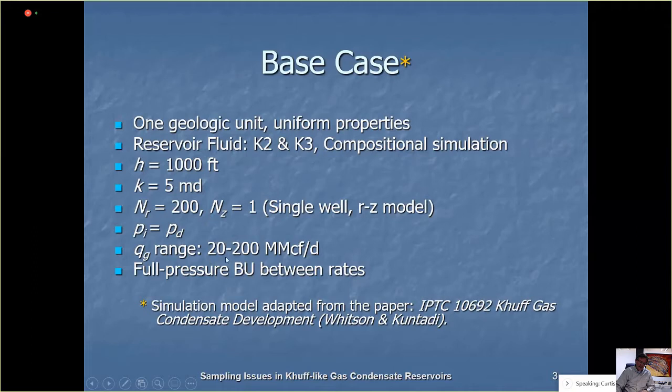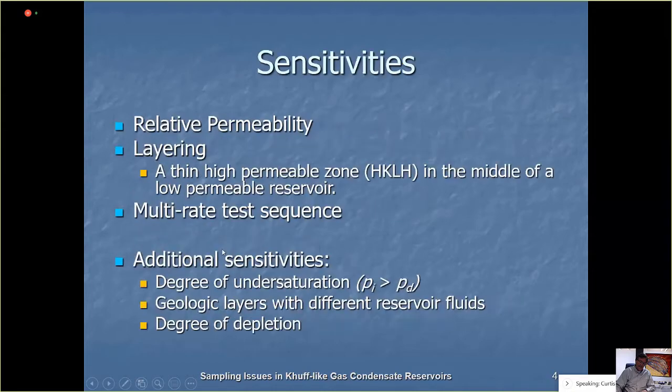Running rates from 20 to 200 million standard cubic per day. We're testing full pressure buildup between rates. And these are initial pressures close to the dew point or equal to the dew point. Sensitivities: relative permeability, layering, multi-rate test, degree of undersaturation.